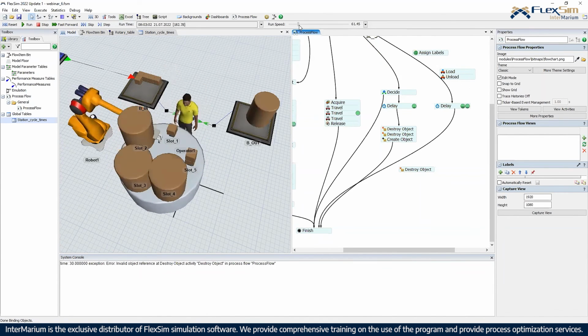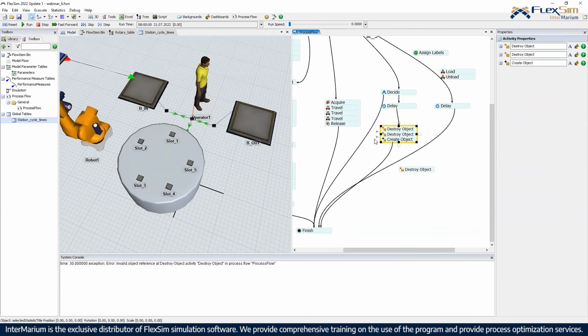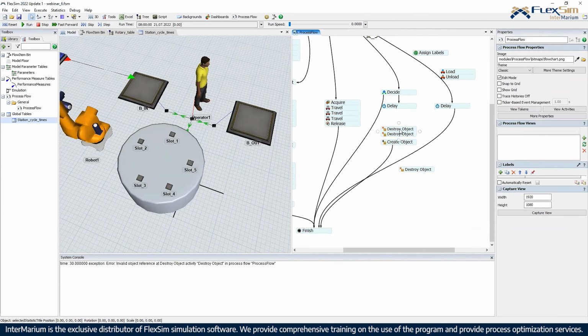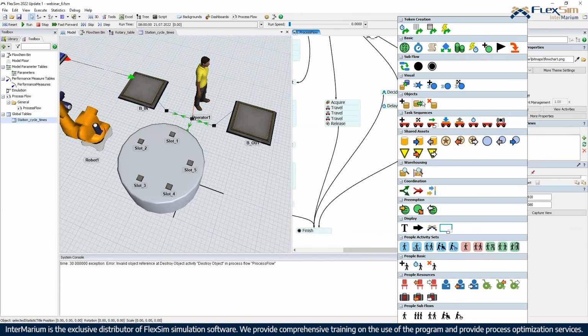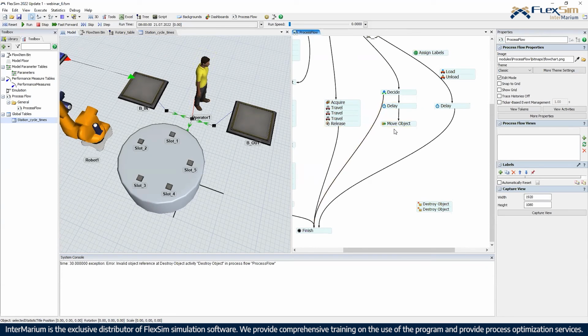So they will become the cylinder. Or if you want to make an assembly the other way, it's going to be not by creating something, but I will just move those objects into each other. So I will move slot.subnode, in this case the second product, to my first product. But I will preserve the global position.